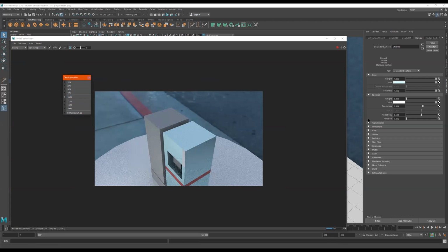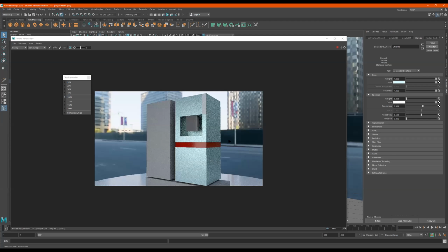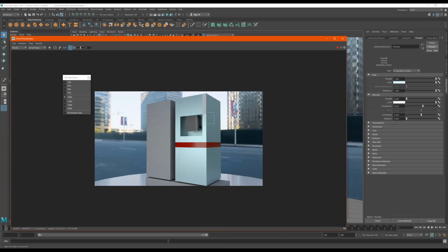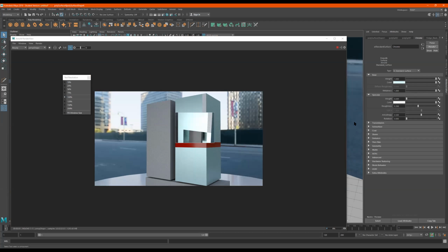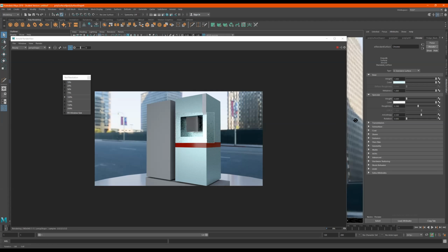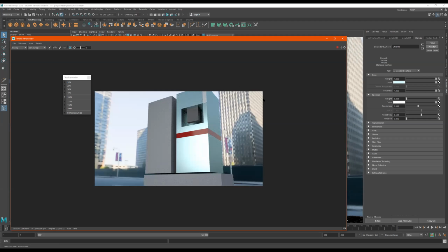And if you do have it on 100, and let's say I have a kitchen, and I just want to see what's going on with the shadows or something like that. I can hold down, is it shift? Yeah, hold down shift and left click and make this, which is a region. Since this is a region, if I mess with it, it just updates in this region. The smaller this window is, the less space it has to compute, the faster it moves. See how I'm moving the camera and it's only giving me that? Now let's say I want to get rid of it. I hold down shift and left click outside of here, and then it gets rid of that.